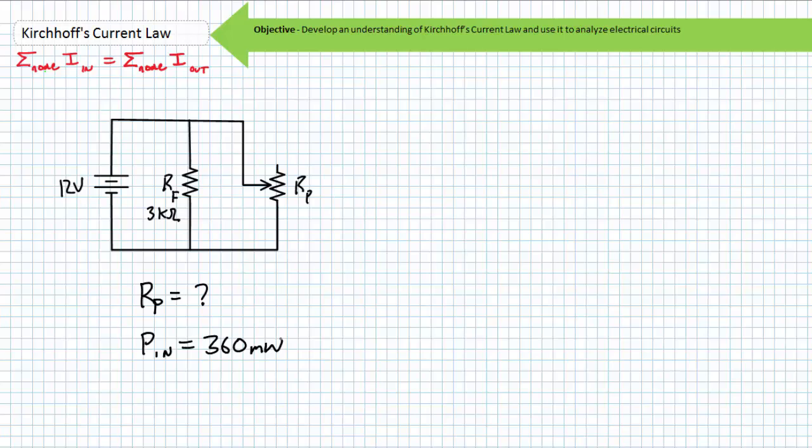What this illustrated example problem is basically asking you to do is to adjust the potentiometer such that the current supplied by the 12-volt source delivers 360 milliwatts to these two resistors. What is the current requirement for a 12-volt source delivering 360 milliwatts? If power is voltage times current, a rearrangement of the power equation yields current equals power divided by voltage. Substituting in the necessary values, we find source current must equal 30 milliamperes.